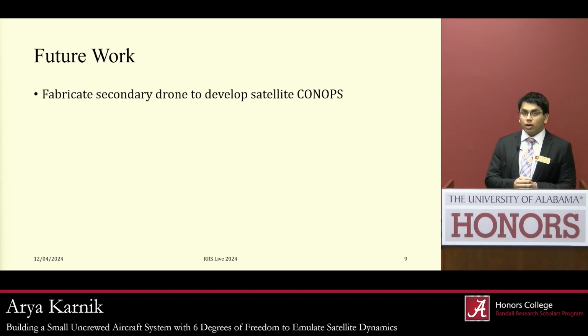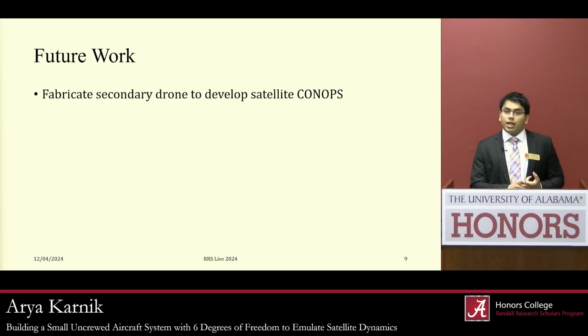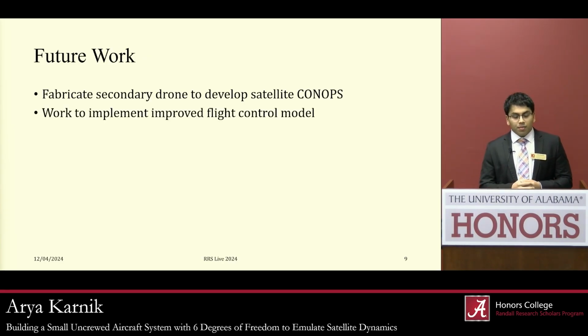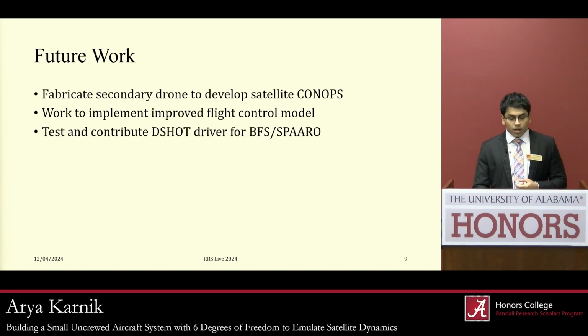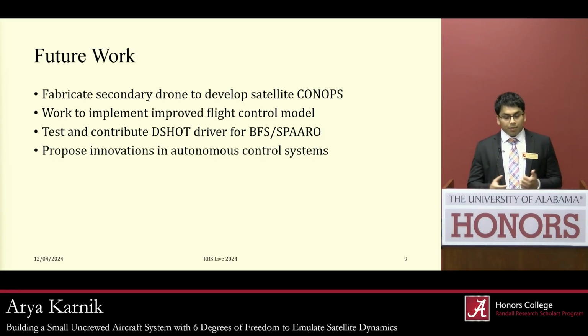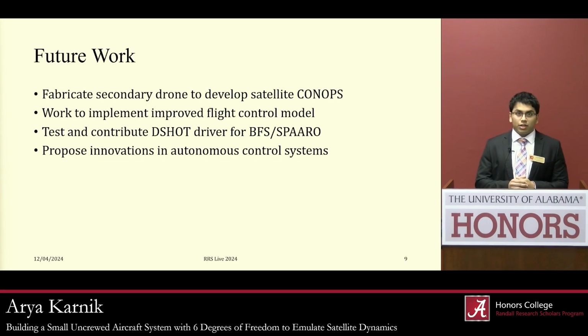What do we actually want to do with what we're achieving? First, we want to fabricate a secondary drone to develop its satellite CONOPS, concept operation plans. From there, we want to work to implement the improved flight control model based on the original paper. We will then test and contribute our D-shot driver that I mentioned for the bidirectional motors for BFS and Sparrow, so we can then also help everyone else move off of PWM and start working on D-shot protocol. We also will then hope to propose innovations in autonomous control systems.